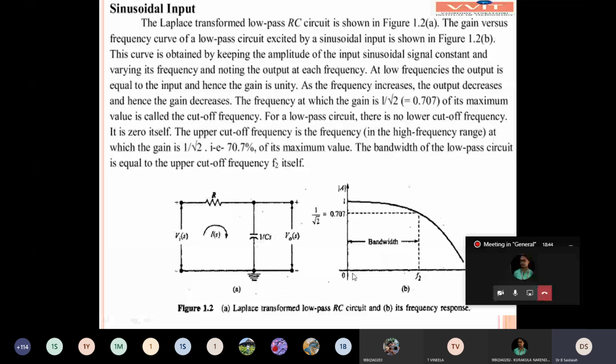At f equal to 1 kilohertz, a low frequency, it is still a higher value, not infinity but some high value. Then when omega is a large value, that means the frequency is large, 1 by a large value means 0. 1 by infinity equals 0. The capacitor acts as a short circuit for high frequencies.